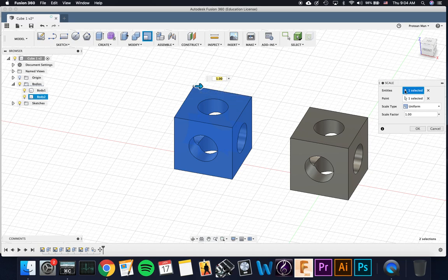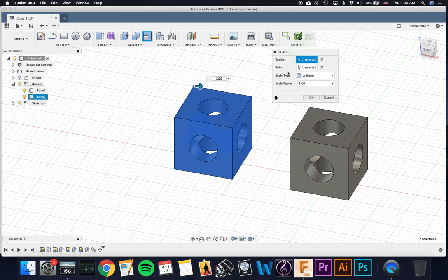You can change it. Right here in the scale dialog box is your point, what I just mentioned. So if I get rid of that, now it's selected, but there's no scaling point. I can move it. I can actually select a spot. The scaling points only attach to actual points, meaning corner points. It won't find the center of the circle. You have to add something else to do that. So we are going to add something in the middle to make this object scale evenly on all sides.